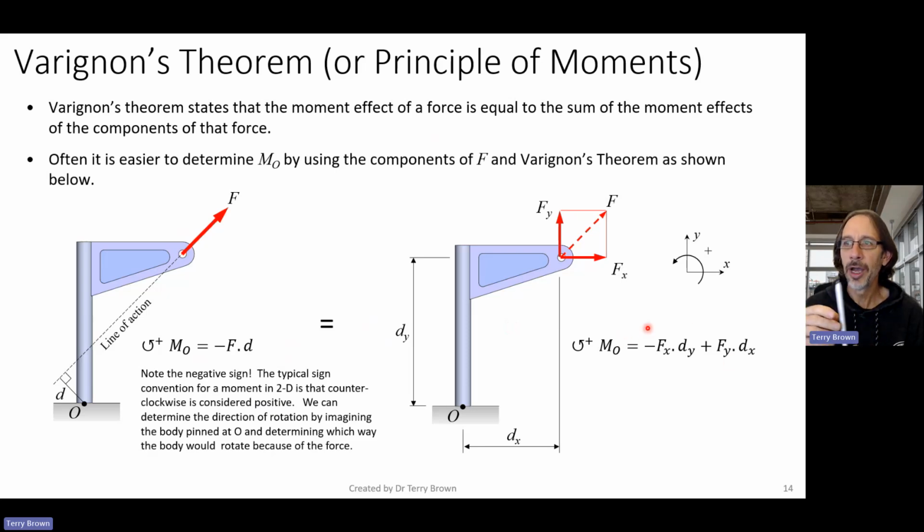And then for Fy, it's a bit harder to do that with a pen, but you just need to remember that it's the line of action of the force, which is down here. The perpendicular distance is now horizontal. So now if we just push Fy, let me do this the right way, over here, push like that, and it goes anti-clockwise.